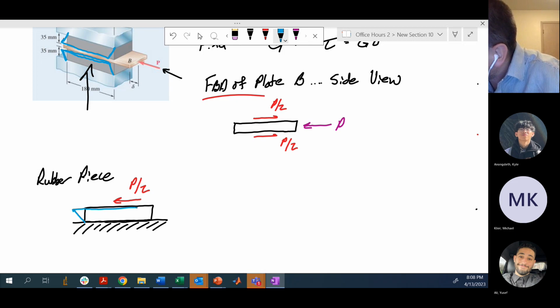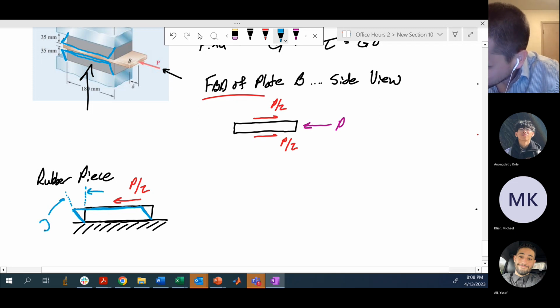Kind of already sort of shown and talked about. And when you see this rhombus shape, again, it should just scream to you shear strain. Okay? And what I mean by shear strain is that we know the definition of the shear strain that we talked about in class is this angle that forms when you have this sort of like rhombus developing. So this is the shear strain angle gamma.